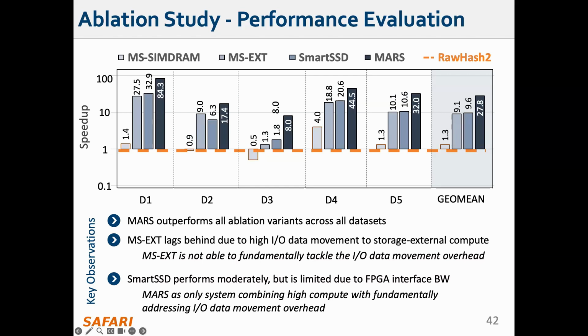In this step in chaining, there are actually a few sorts that are of medium size, so a few kilobytes. For those, we have registers near the mergers such that we can do round trips there. And if it is a longer sequence, then we transfer it back to the DRAM, and we hide the data movement latency by placing it such that we always have the data ready when we want to merge. Yeah, thank you.